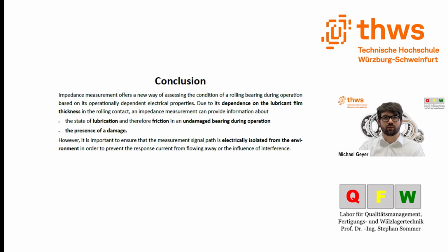Due to these test results, it can be said in conclusion that the impedance offers a new way to assess the condition of a bearing. The dependence of the impedance on the film thickness and stability provides information on the lubricating state and the presence of a damage.